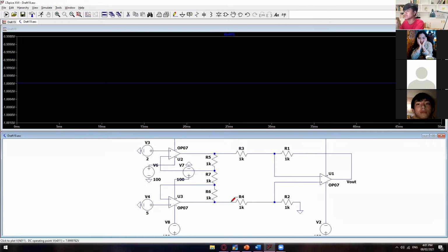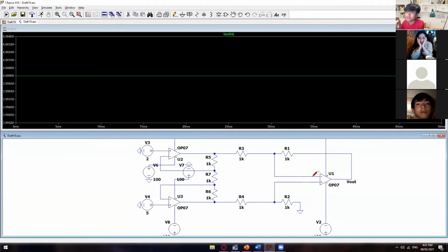And as you may recall, amplifiers or op amps, operational amplifiers, tend to equalize the two inputs. So mostly the input here in negative is the same as this positive input. So as you can see, if we click this one, it's 4 volts, and for the positive, it's also 4 volts. So that is why this 1 volt is not the same as this one anymore.